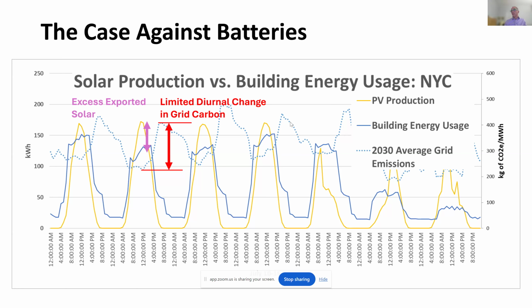So if you're using a flat virtual rate, you can't show any benefit to using thermal storage because it's a flat rate and you're going to use more energy to store that energy and then release it. So any round trip efficiency, whether it's 10%, even 0%, you're not going to show a benefit of adding it.